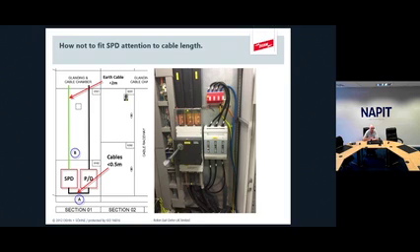It's in a metal box. It would have been far better just to bolt it to the DIN rail in the metal box itself. You can use that nut and bolt arrangement as an intermediate earth terminal, and everything is cross-bonded, and it makes no difference whatsoever whether you took it to the MET or the case of the distribution board or the metal consumer unit. That's perfectly fine.